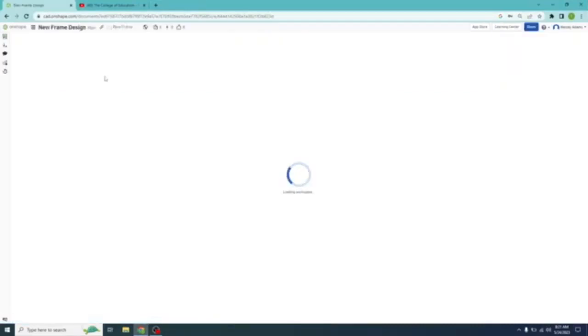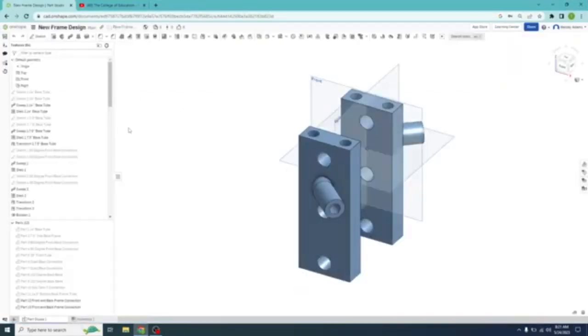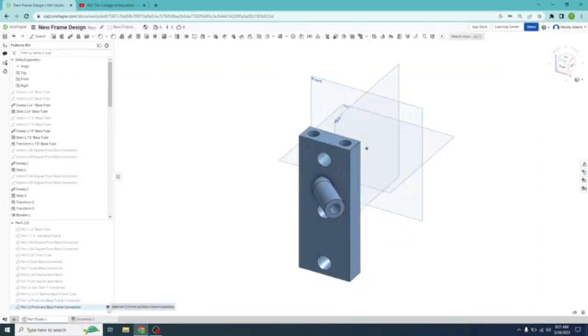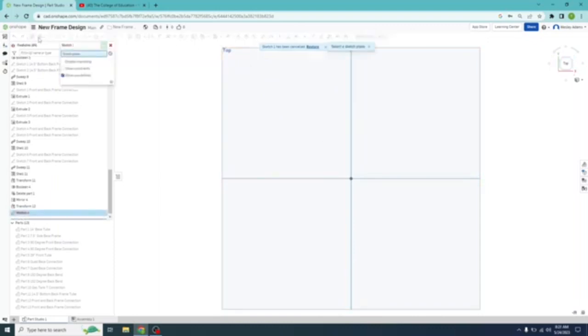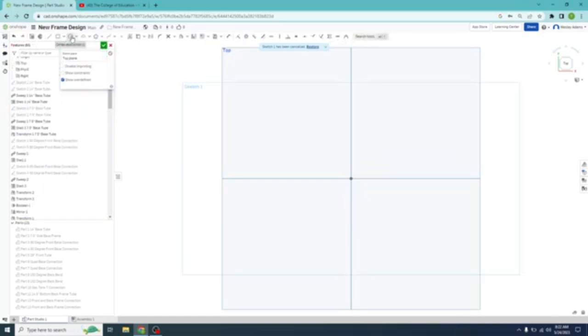Open up our file. We're going to create this top spar mount. Let's turn the last two off to top. Let's create a new sketch. Let's select the top plane, left click on the circle, hover on the center point of that plane. So hover on the center point of the plane, left click, drag that out. Hit escape, left click again.